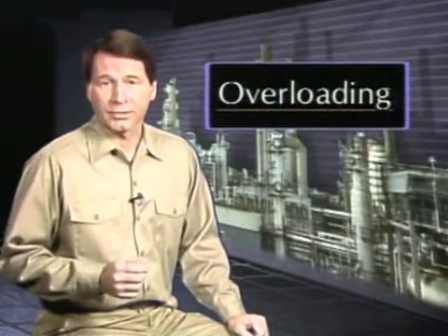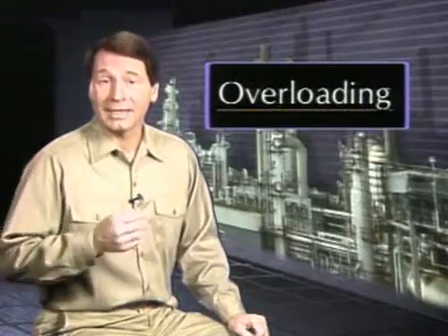If a system's feed rate is too high, overloading can occur. Overloading is a condition in which the vapor rising up a column is impeded by the liquid flowing down the column. If the feed rate to a distillation column is too high, overloading and flooding can occur. But the performance of a distillation system can also suffer if the feed rate is too low.